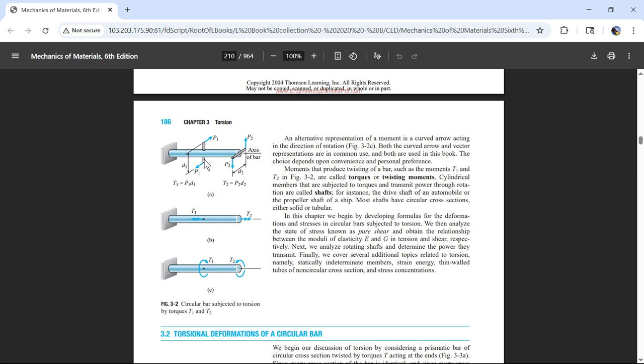Now over here, I'm going to go half the distance, half this D1. So D1 divided by 2. I'm going to go from there to there, multiplied by this force. And with the right-hand rule, my thumb is going to be into that direction, and that'll also be clockwise. So that'll be negative. So I'll have this negative torque, P1 times D1 divided by 2, added to this, P1 times D1 divided by 2. And if I add those two halves up, then we get P1 D1, because we had P1 D1 divided by 2 plus P1 D1 divided by 2. That adds up to P1 D1.